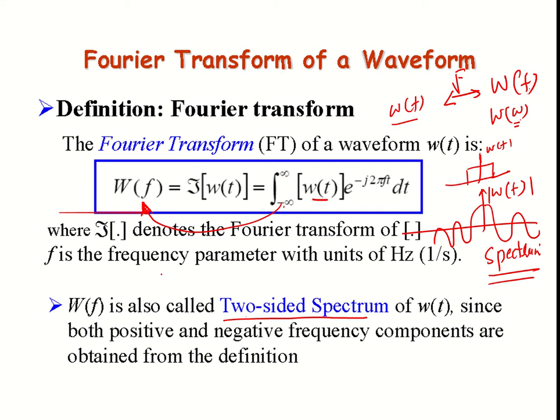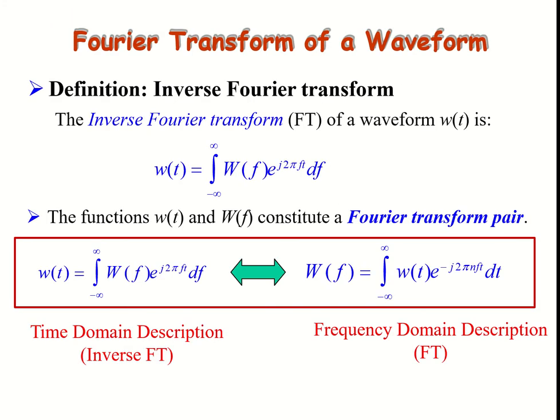And if we want to calculate the inverse Fourier transform, the Fourier transform of the signal is multiplied with exponential power j 2 pi f t, and then we get the inverse Fourier transform of that signal. Usually we use the inspection method or partial fraction techniques for the calculation of the inverse Fourier transform instead of using this integration formula. So that is our usual approach.